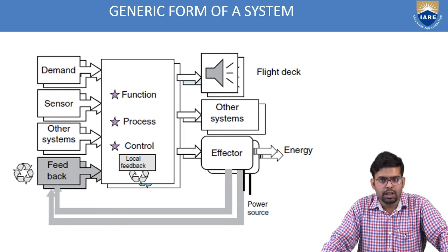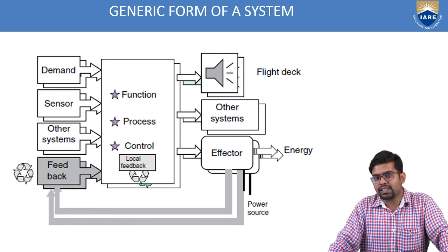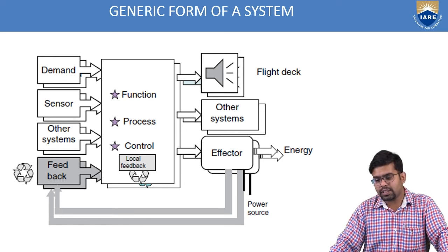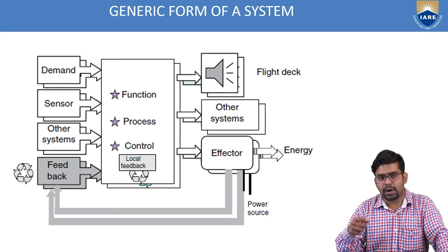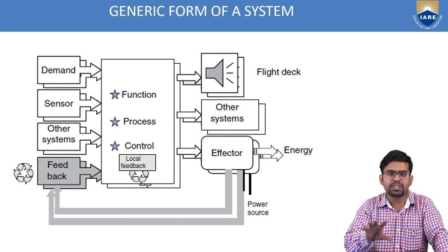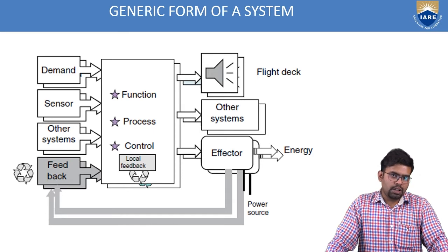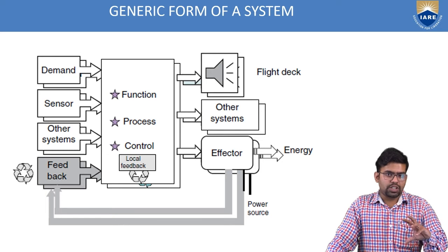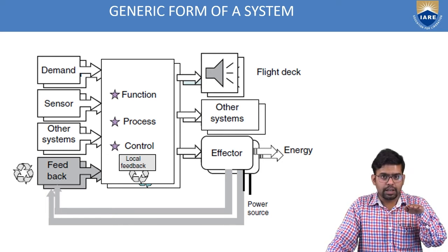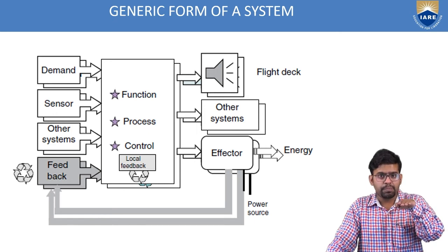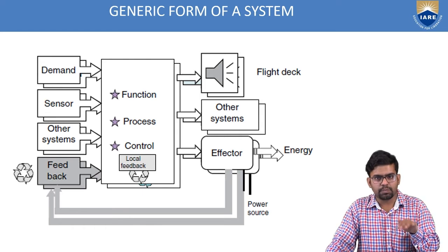For example, let me come back to Boeing 737 MAX 8. So Boeing 737 MAX 8 actually had a problem with its MCAS system. MCAS is an automatic flight control system, which is a part of avionics subsystems or mission systems, both of them. So what happened was, due to the change in position of engines over the wings, the aircraft was giving some pitch up movements, which was not in its nature. It was giving some pitch up movements.